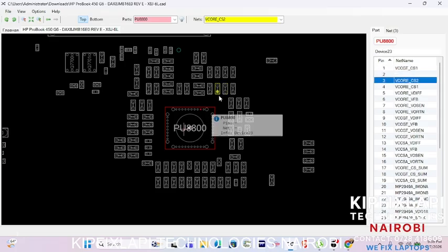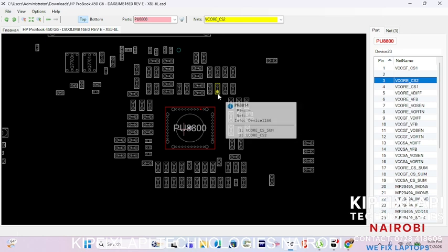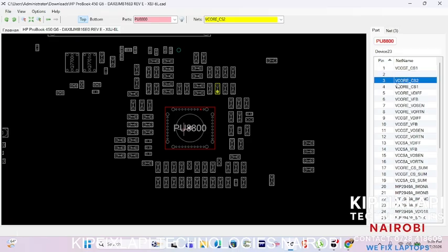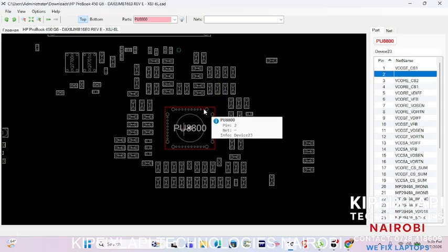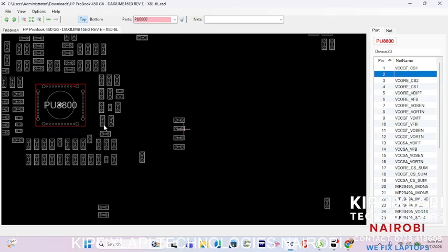Pin number 3 connects to this. You see this yellow part, it shows you that it connects there. And again, we have a net, the function of that pin. Pin number 3, that is its work. You can see the pin number 2. When you click it, it doesn't have anything. So it means that is an NC pin. NC pin means not connecting. It doesn't connect to anywhere.